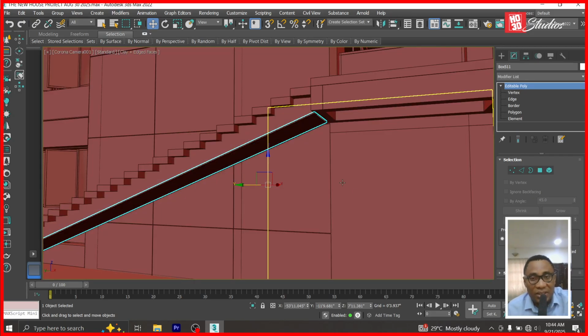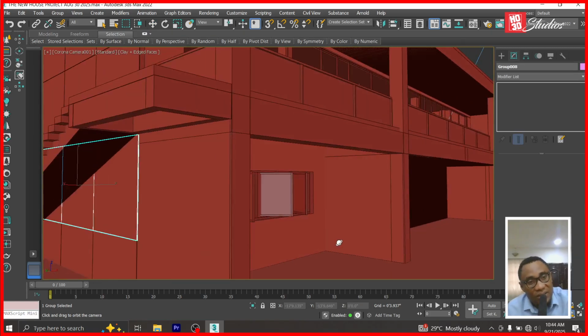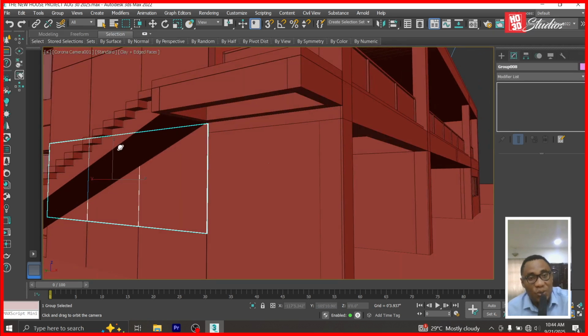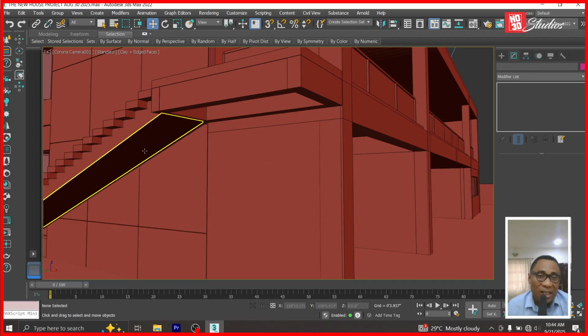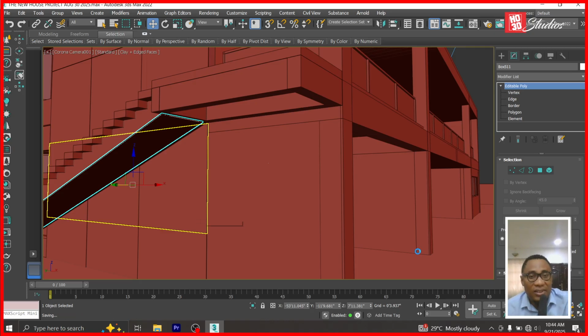Let me see. What I have done is this place is now covered. You can see it's now covered. So you can't really see the beams, but they are there. This will be covered with, could be cement board, and then they would screed with emulsion and white powder, and then they would get this very smooth white finish. So that's just what I've done.